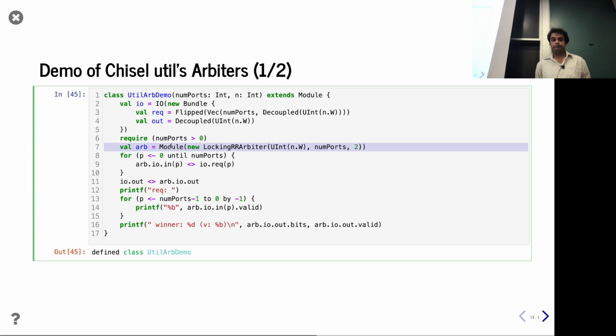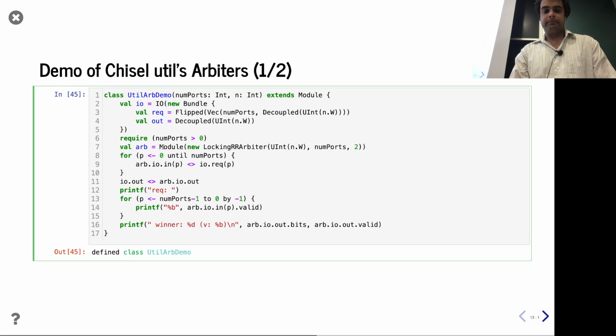And that's usually okay if that thing ends up being called eventually inside of a module. In the case of some of these components from the Chisel utility library, occasionally you kind of wrap them in a module. You have to forgive me for not remembering the exact Scala language embedding reason why this is necessary, but I'm pretty sure this is not going to work if I remove this. We'll find out.